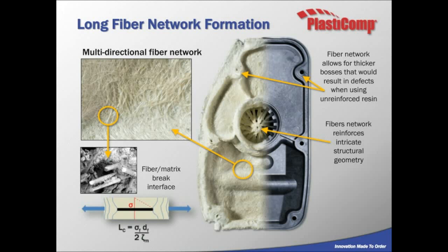Now, the longer these fibers are into the opposite side of the break interface, the more energy it takes to cause the break. And this is another reason you want to make sure you're getting that fiber orientation perpendicular to that break alignment. Hopefully that makes sense.